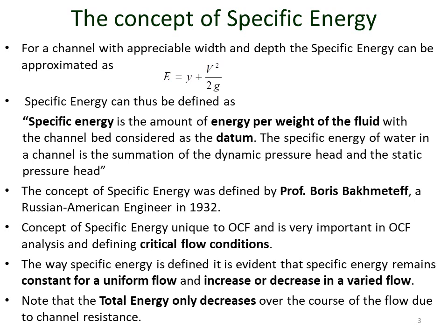The second sentence here is also very important. As you can see from the expression, the specific energy is the sum of the static pressure head given by Y, the flow depth, and the dynamic pressure head given by V square by 2G.